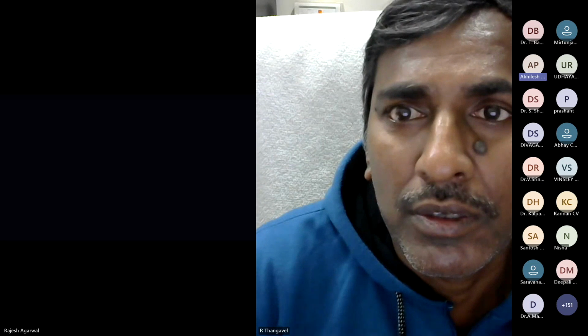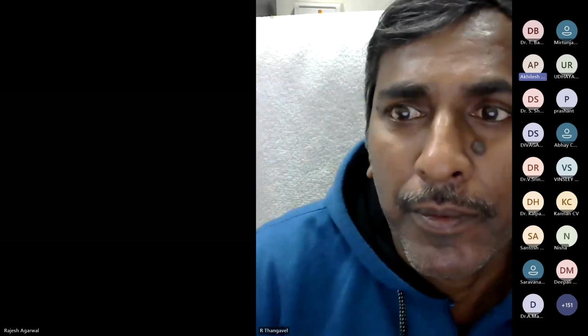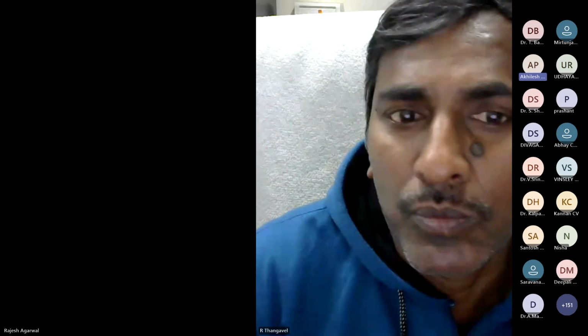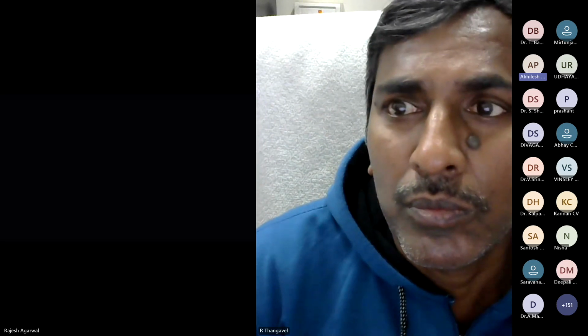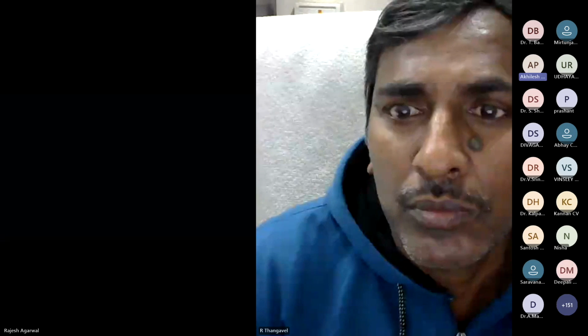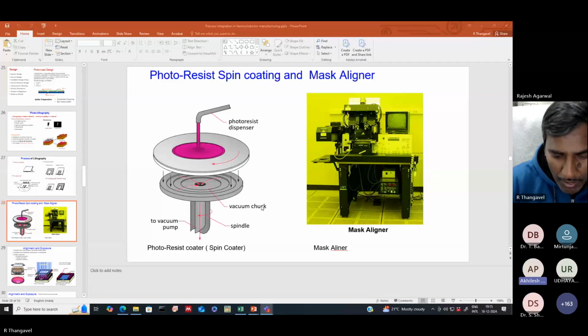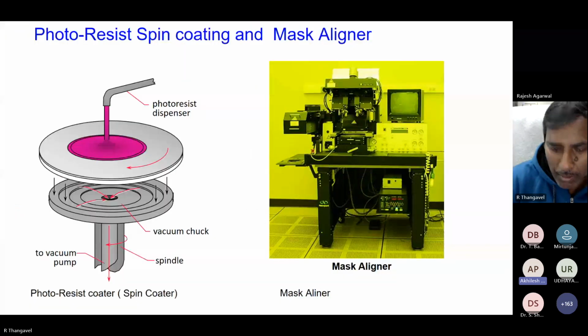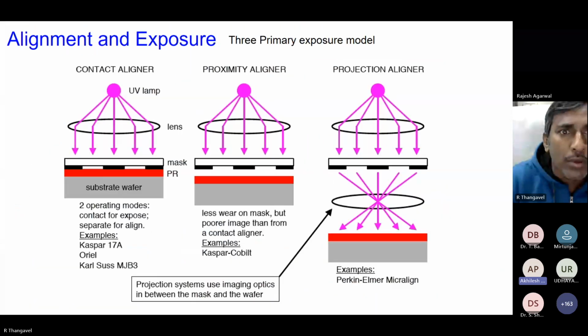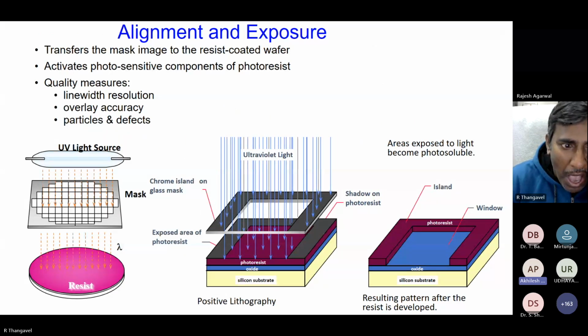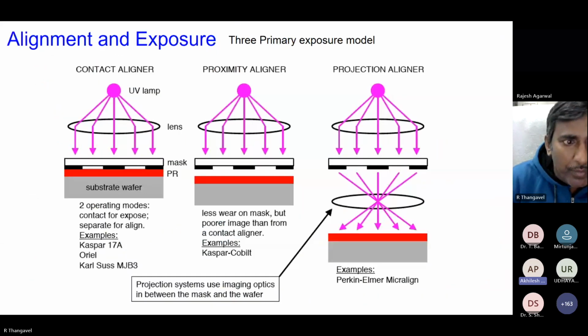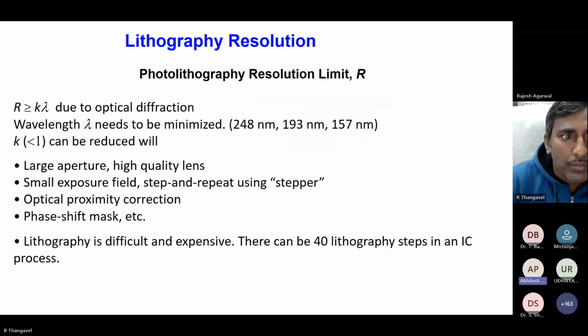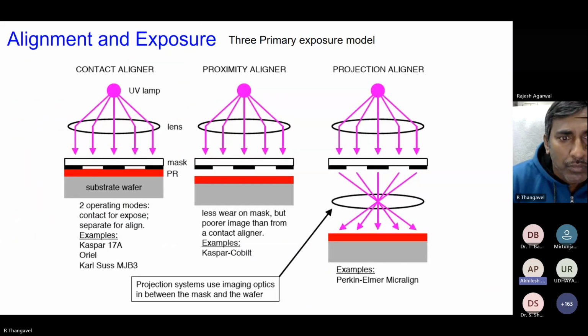Now, the basic concept of etching. Etching is the process of removing material in a specified area through wet or dry chemical etching. Basically, etching is similar to chemical vapor deposition, except the materials are removed. Here, what happened in the etching process? The etchants have to diffuse onto the film, a reaction will take place, and the reaction products and byproducts are mass transported and have to come out from the wafer.